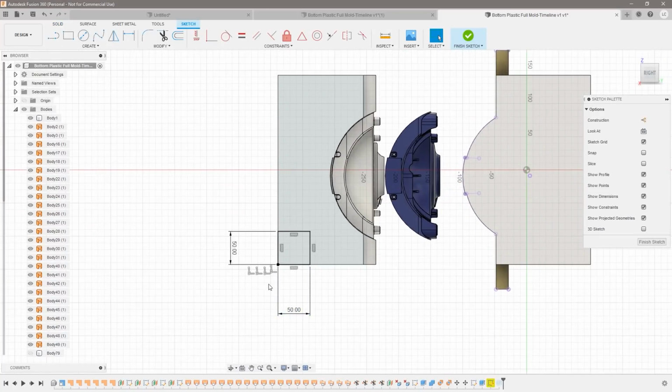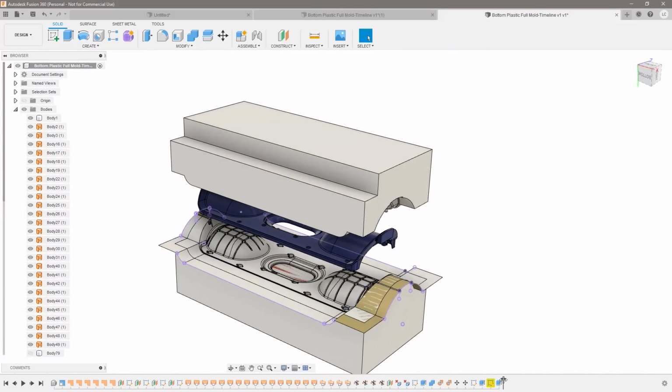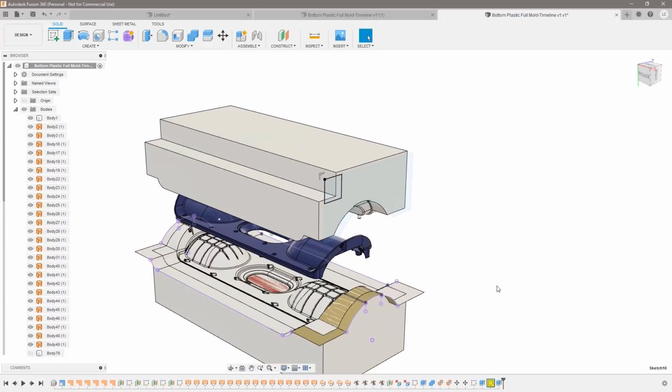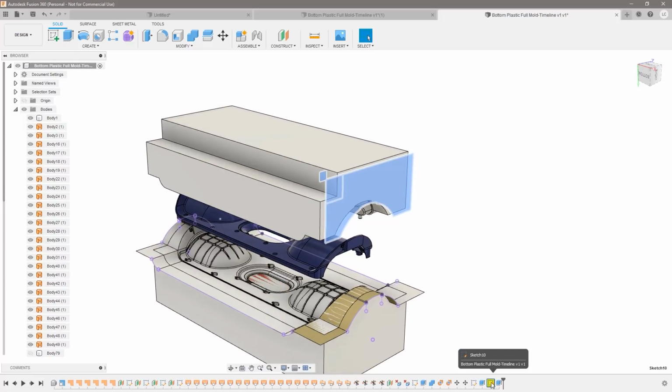you will see that everything looks somewhat normal, but of course that sketch is sitting where? That sketch is sitting out in space. It's having a warning. You should always go in and fix these. And again, the idea is when Fusion is solving, it's solving from the first base feature. Every time it's recalculating, it's calculating every single step. So you can imagine when it comes to this point that now it's using cache. Now it's trying to recalculate things. That's extra resources, no need for it.